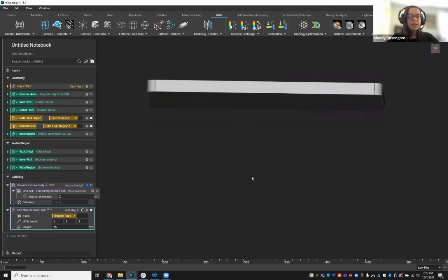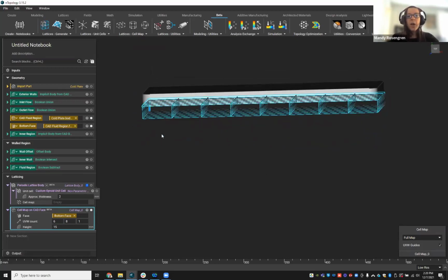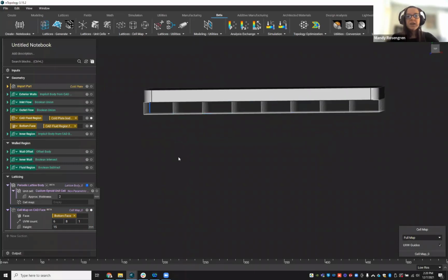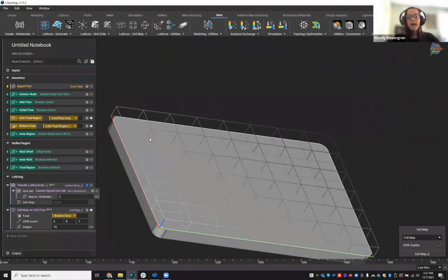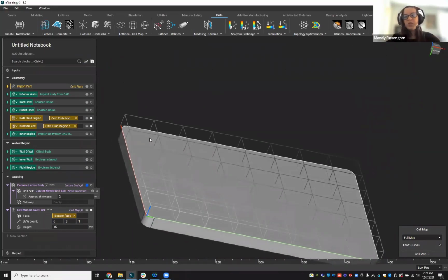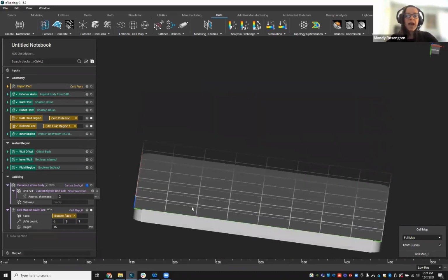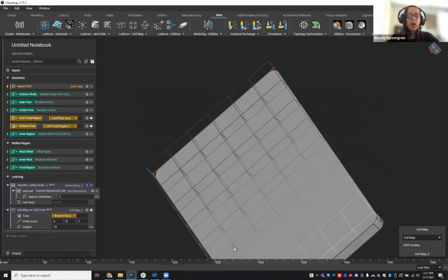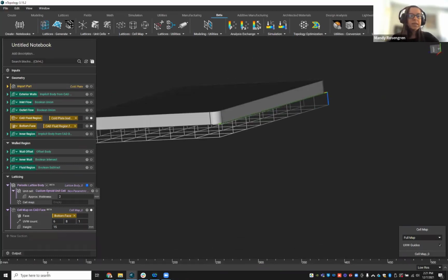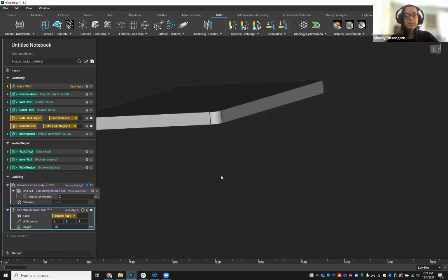And let's see what this looks like. And what we can see is this is actually going below our part. So what we're going to actually need to do, and the reason for this is because we'll have that height that's going to be normal to that surface. And since our bottom face, that kind of positive side, is going to be below our part, we're going to have this height that is above our surface. But we want to go within this full region. So instead, I'm going to change this from positive 15 to negative 15.